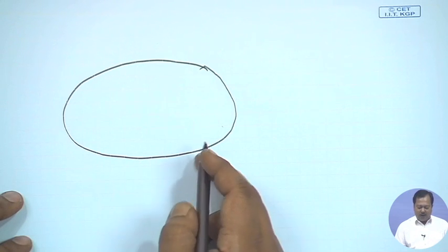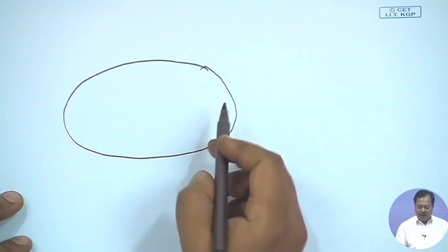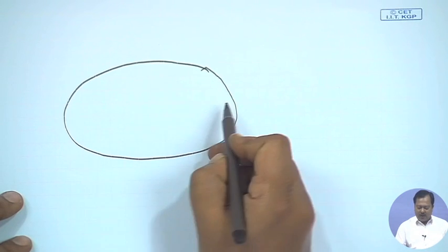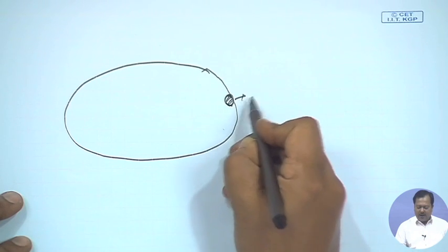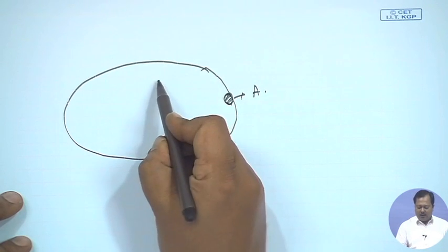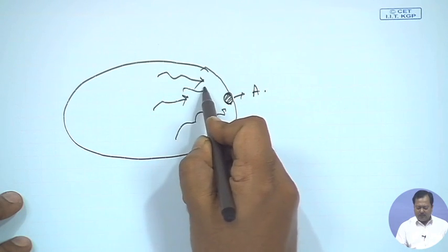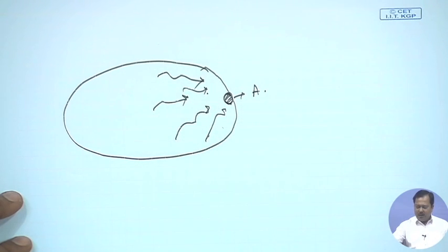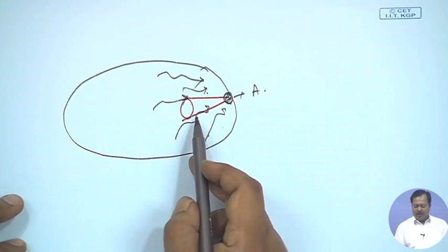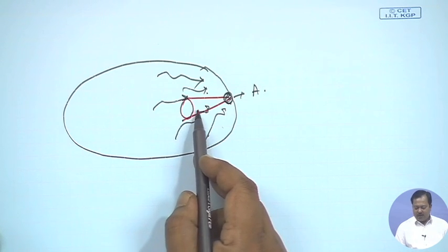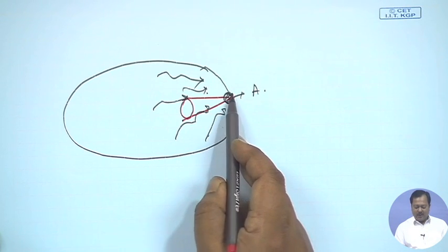It is made of a black body, and inside it is radiating due to its temperature. Let us say we want to calculate what radiation is falling on a surface of area A. The radiation is coming from all different angles over this, and we define one unit solid angle, calculate the radiation coming through this unit solid angle, and then integrate it over the incident area A.